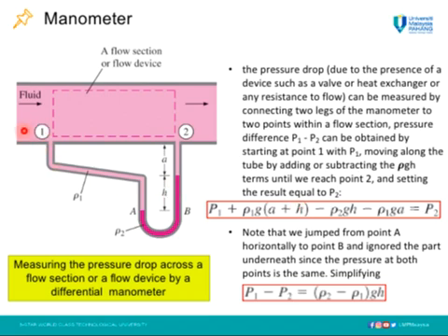For example, here we start at P1, the pressure at point 1. As we go down here, we add the ρgh of this fluid, which means the density of fluid 1 times gravity times height. The height here is from here to here, A plus H. We are here now, so we can jump to point B as it is at the same height and it is interconnected by the same fluid, which has the density of fluid 2.